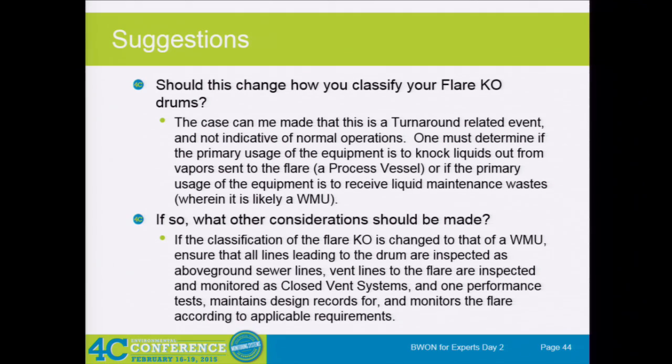Well, on your flare lines, on your vapor lines, depending on what the flare is, a lot of people have different facility flares. Between the flare knockout pot and the flare itself, do all of your facilities have that line in for Method 21 monitoring? I would say it's greater than 60%. So maybe not everybody. And if not, they're doing an annual visual, but not an annual Method 21. I would say it's more than not. So not all facilities have it.